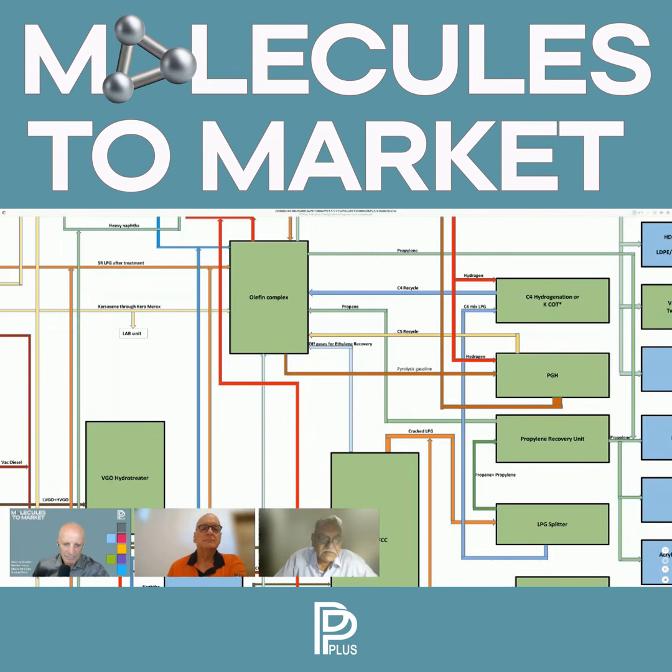In EPC mode, like typically you do in the West, we develop a feed document, select an EPC contractor, and this is a time cycle. This part of the activity of preparing a feed document, then lining up a contractor takes time. I know in the West it takes 18 months for you to come to a feed state where you can say plus or minus 10%. In India, we do it very fast, but still it takes time. But once the feed document is prepared, to line up the EPC contractor is another time cycle itself. In India, this varies between 6 to 8 months.